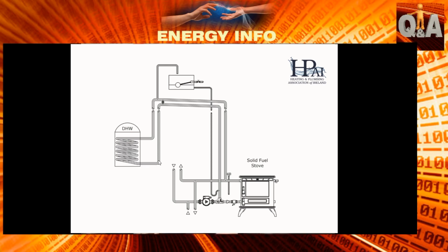The little 1/2-inch bypass valve you see here is a very good idea, because if you bring pipes up and across an attic, the danger is that you would lodge air in the return pipe. The vent pipe has an open vent obviously above the tank, but the cold feed with a little 1/2-inch bypass valve between the two, barely open, will allow any air that's trapped in the return pipe to rise up from the return to the flow and then out through the open vent.